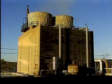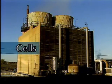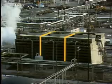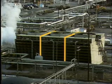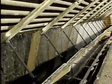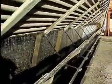Now, regardless of the type of cooling tower, there are some components that are common to most towers. For example, many towers are divided into sections called cells. This tower has 3 cells. Each cell contains all of the components of a single tower, except they share a common catch basin. Each cell of a tower can be operated independently, so the proper amount of cooling can be maintained by taking one or more of the cells out of service or placing them in service.